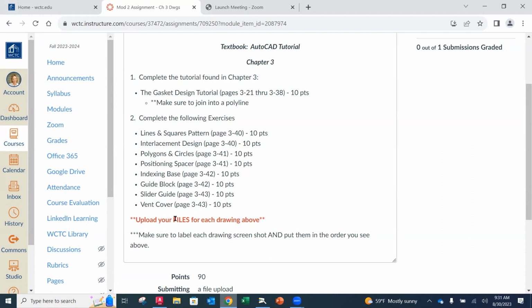The reason I want to see them is because we're exercising some of these modifies and using object snaps. I want to be sure that corners are coming together, and that we don't have overlaps or things that aren't quite there. I can only do that by zooming in on the geometry. Yes, it's going to take me a little bit more time to look at these. That's okay. It's really important at this level that we are doing the good stuff, and I want you to pay attention to that too.